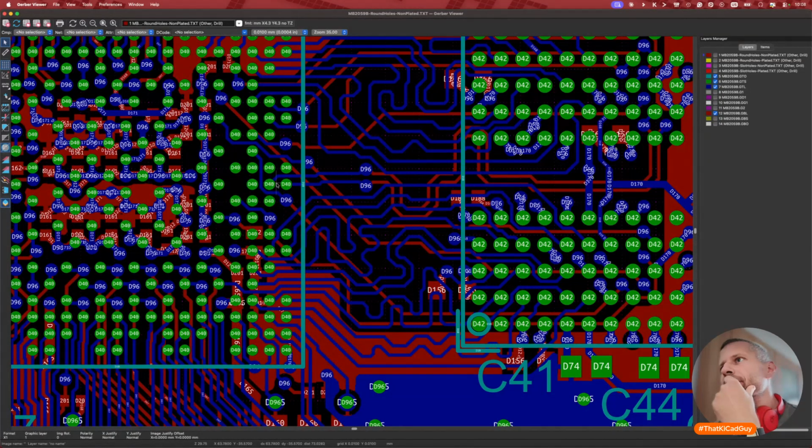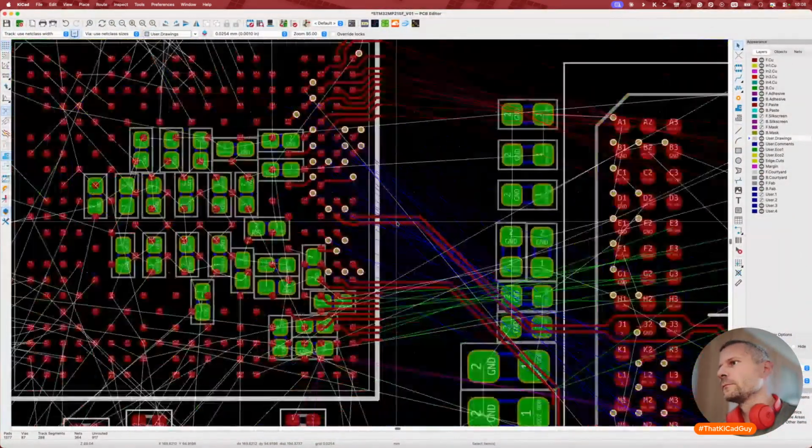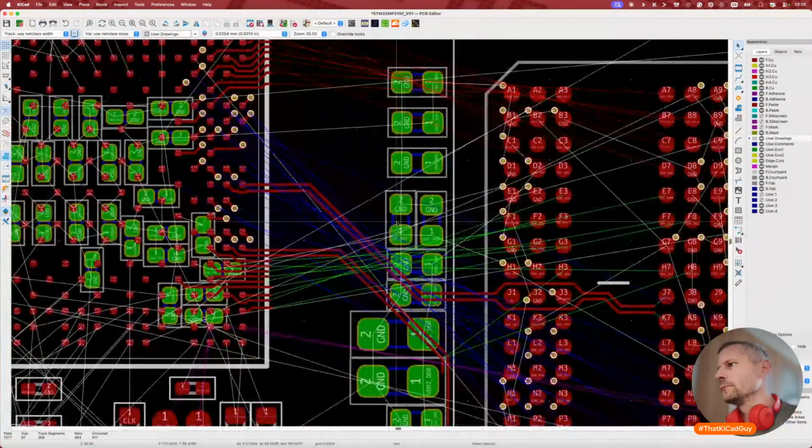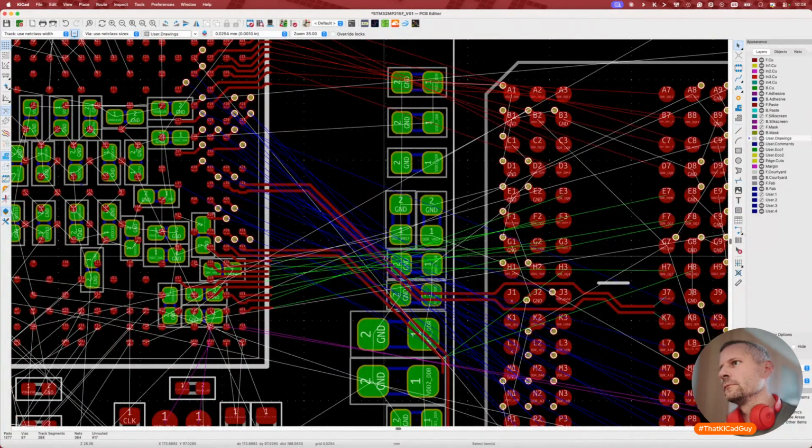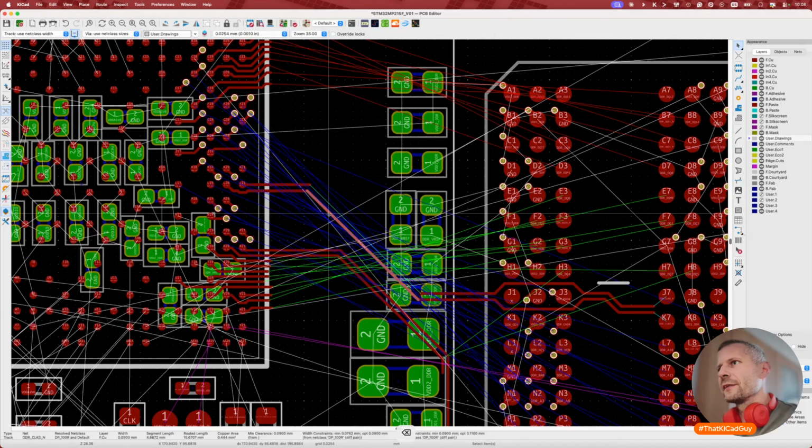Okay, these 2, and there is a clock, there is a via, and no reference plane return path vias. I don't know why. And here is a clock signal to other vias. And okay, so we can place a via to the clock signal, so we can avoid the mess here.